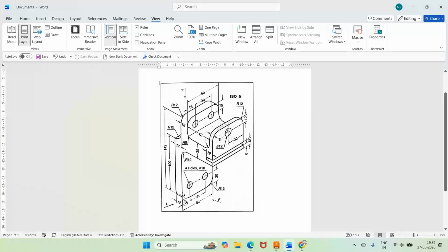At least he should give this particular dimension, which is 10. Then from which one do we have to take this? Neither has he given this height. He has given 142, but this is only 42 mm from here to here. But this 42 does not match any of the other dimensions. So we need to assume this dimension at some point. So from here it is 25.